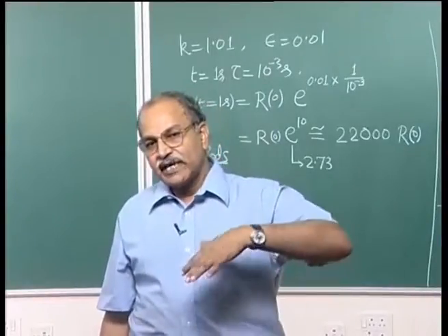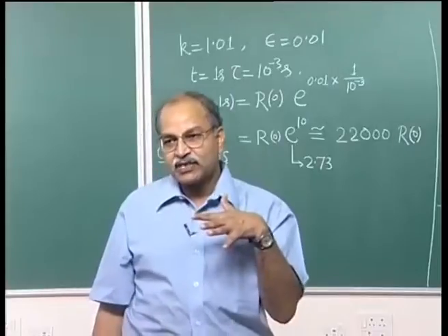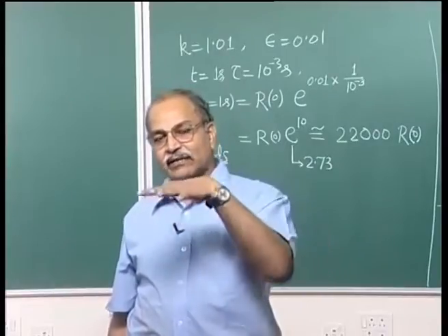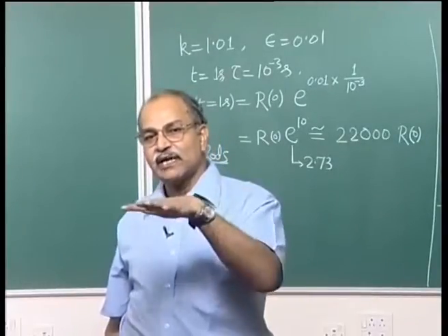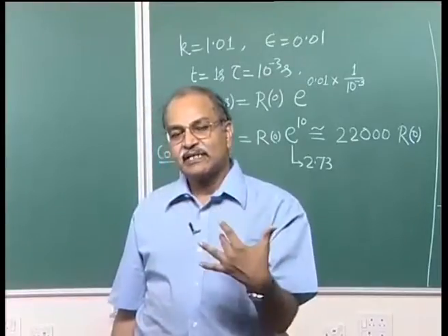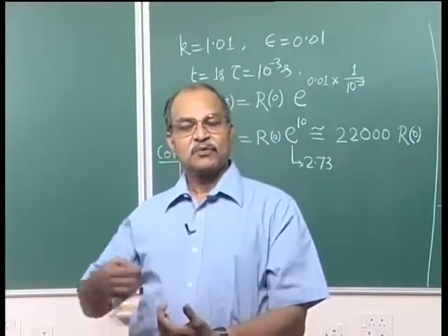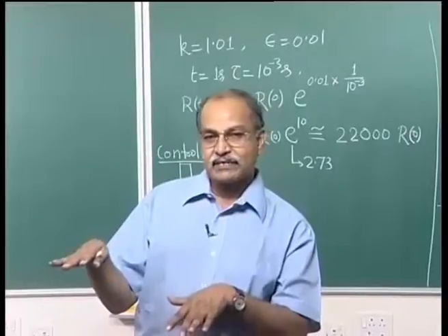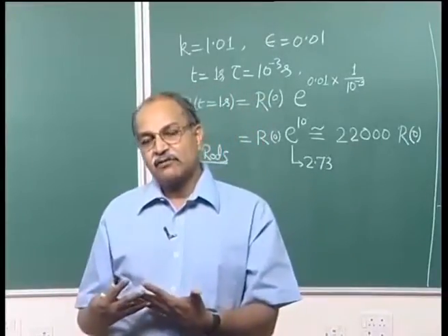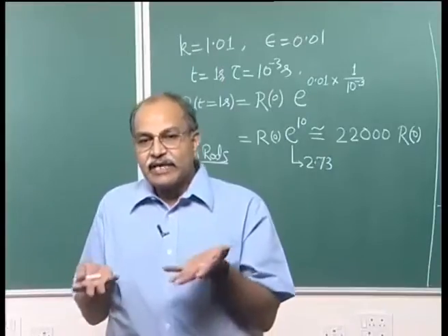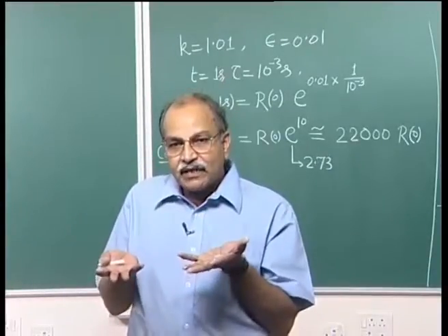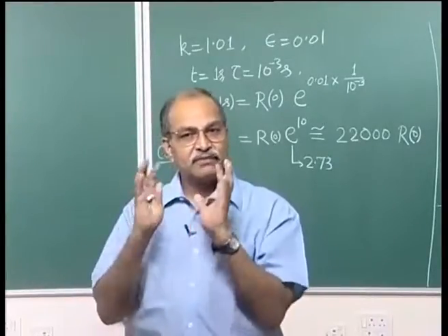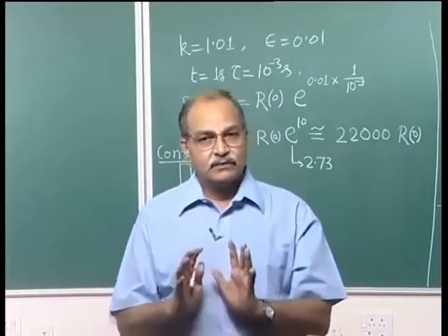And if the rate has to be increased, if k has become less than 1 and you want to make it k equal to 1, that is called critical. When k is 1, the reactor is critical, and if it is less than 1, it is called subcritical, and if it is more than 1, it becomes supercritical, which is dangerous. So, if it is subcritical and you want to make it critical, you want to increase the rate of these fission reactions, these cadmium rods are lifted up, so that a smaller fraction of those rods is inside the core.